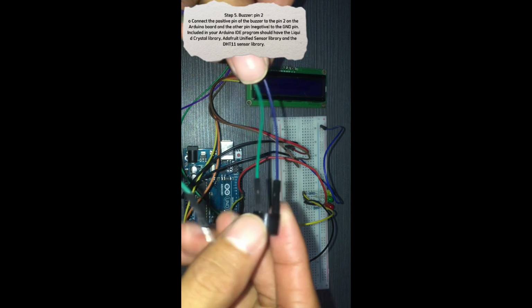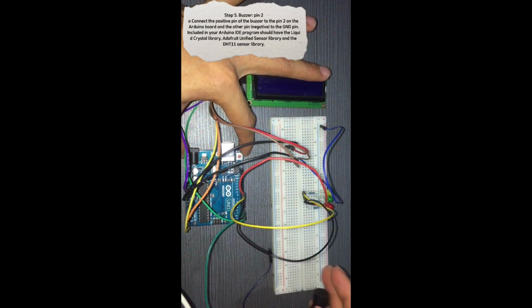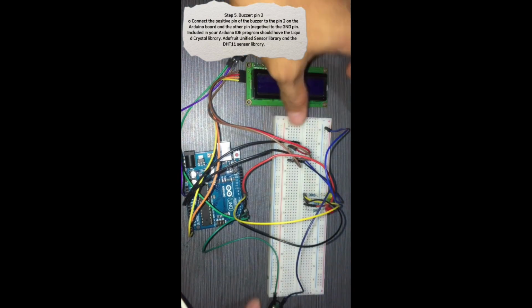Step number 5. Buzzer, pin 2. You connect the positive pin of the buzzer to pin 2 on the Arduino board and the other pin, negative, to the ground pin. Included in your Arduino IDE program should be the liquid crystal library, Adafruit unified sensor library, and the relevant sensor library.